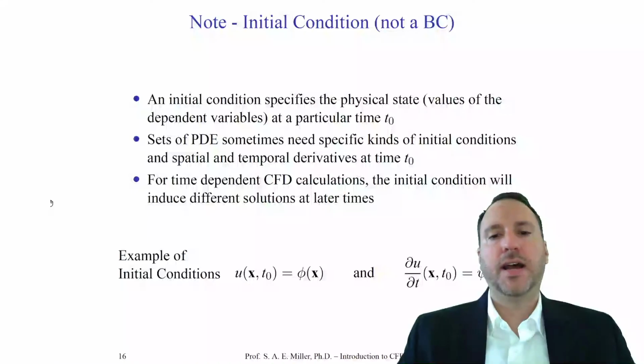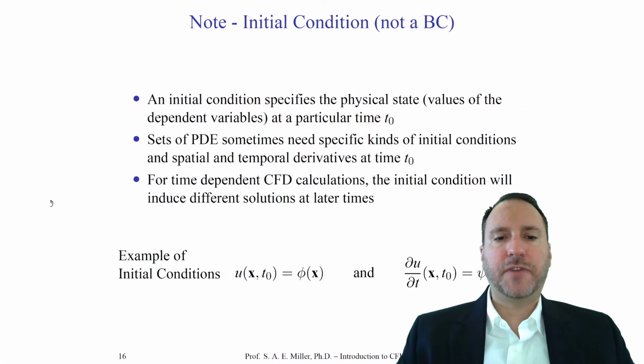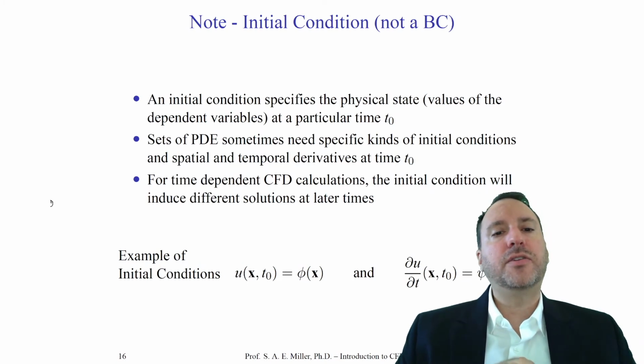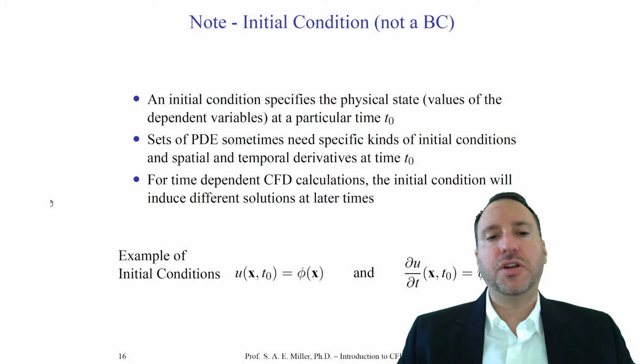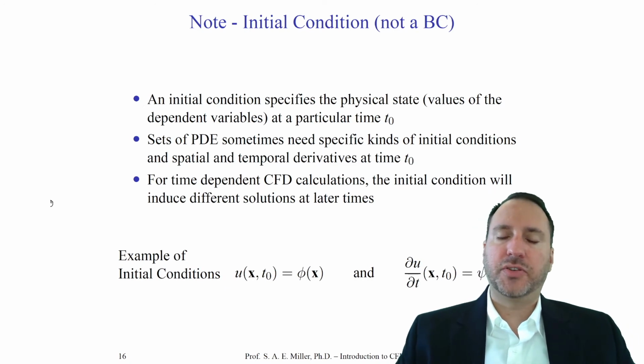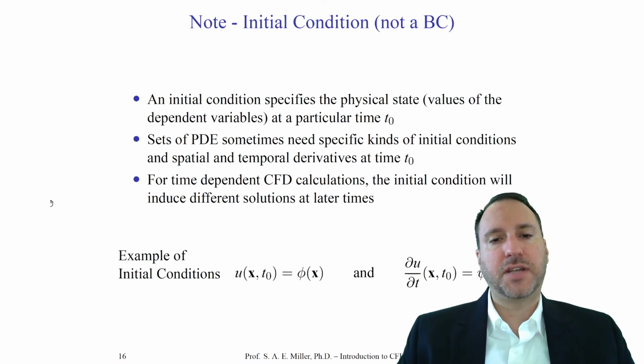Now, for time-dependent CFD calculations, the initial conditions will induce different solutions at later times, especially for turbulent flows. You can change any value of the initial condition and find a completely different solution at a later time t greater than t0. So the specification of initial conditions is so important that you can even specify an initial condition where there will be no solution possible. That is, you've specified an unphysical set of the solution at a particular time.